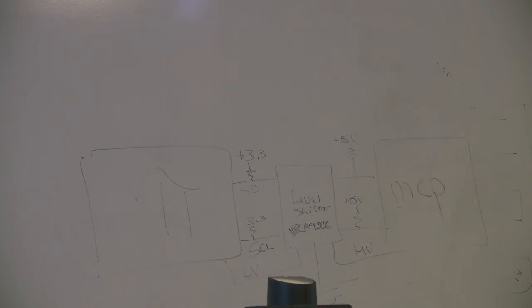We're going to do some string of LEDs, and then suppose we had something that isn't going to draw a lot of current, but I don't need a MOSFET. We're going to use the port expander because we want to make sure this 5 volts doesn't go to the Raspberry Pi, but will control our things. I just want to give them a bunch of different ways to hook things up.